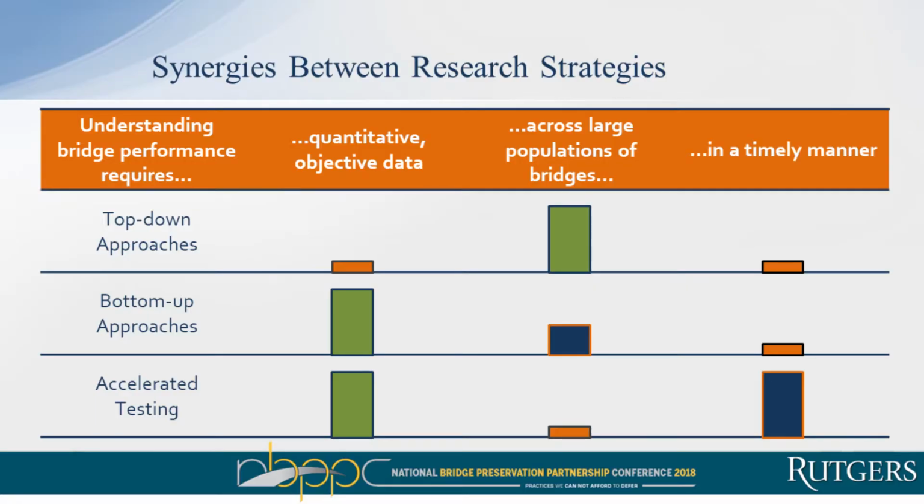One, we can get really good quantitative data. So I can instrument this from construction and look at intrinsic forces that are generated in the deck, not after the fact where I go and put a sensor on and don't measure what stress state the deck is in after it cures. That could be a pretty good indicator of long-term performance perhaps. So we can do a really good job there.